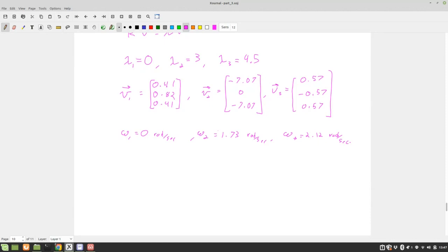It will exhibit that mode, but it means that mode is a DC mode. So you're right. Your first frequency is the whole plane moving up and down. Does that make sense? Your first frequency is not a V. Definitely not. So your first frequency is the whole plane moving up and down. But wait, it's not what this shows. This shows kind of a V-shape, right? But what is this? It's the direction, but what is V particular? Is this the mode shape?